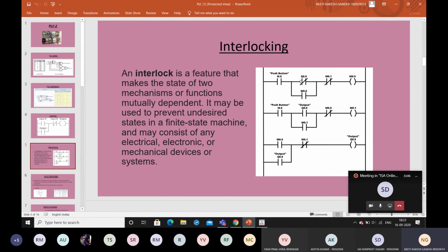This becomes an open circuit and this is going to open up and this is going to shut. As soon as this shuts and my push button was on in that split second, my M 0.1 is going to be on. As soon as M 0.1 is on, it's becoming a latch function by itself. It's opening this rung and this rung. So in the end, even this is going to be off, but the last thing that you will see working is the light of the second room.